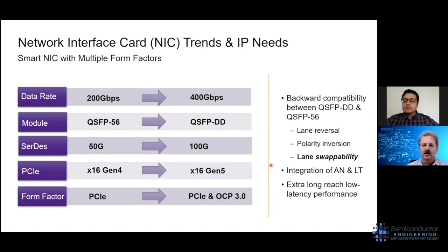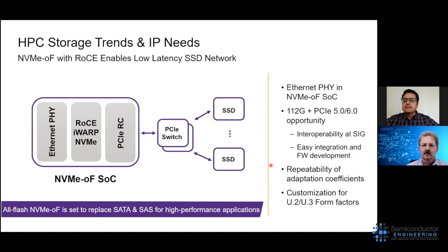Yes, and that's put new requirements on the way data is stored. Data is stored traditionally on SSDs using flash storage, solid state drives. And PCIe was adopted with SSDs in about the 2014 to 2015 timeframe. With the PCIe switch, the SSDs were scaled within a rack. So multiple rack units using PCIe as an interface can be connected together, and the processor can use all this storage as server storage and can directly map using firmware memory registers.